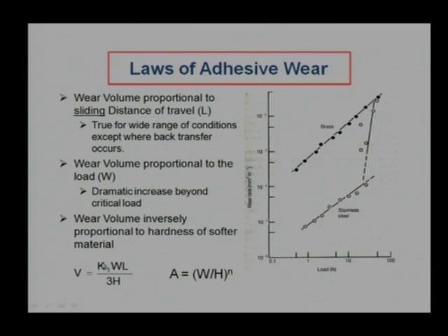We know there is one wear constant K1, and if we introduce this one, there will be two wear constants. To figure out the two wear constants, we require many more experiments, manifold experiments, to get reliable results. So, when we are working with only one pair or two pairs, we can use this generalized equation. We use input W, L and H and figure out the value of K1 after doing a number of experiments and reliably believing in it after that.